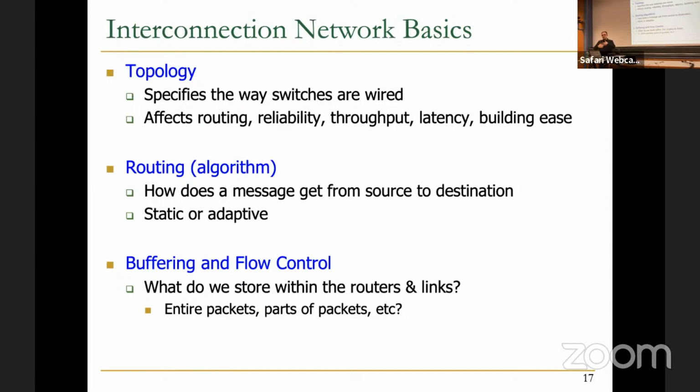So this needs some communication. There should be some buffer, for example, in the downstream router, such that the downstream router can buffer your data if there is a blocking. But that being said, there are also some network designs that you can have bufferless. That is actually one of the very exciting works that we're going to cover next week, where your network does not have buffers, essentially. And that involves a lot of exciting topics in flow control and routing that we're going to see later.